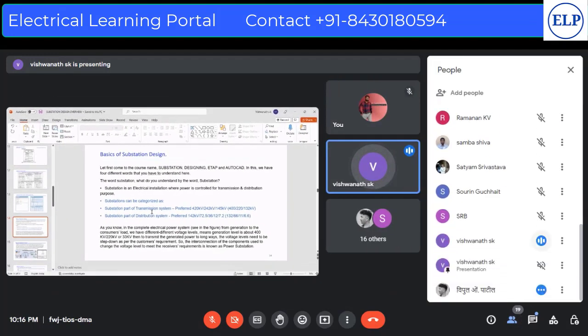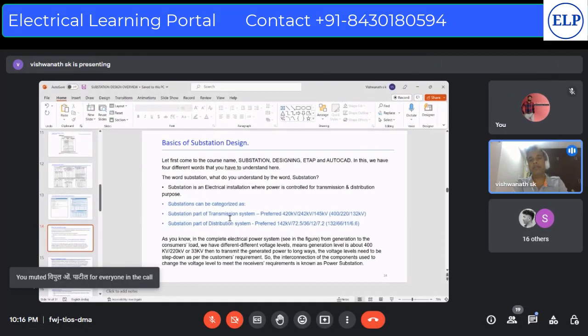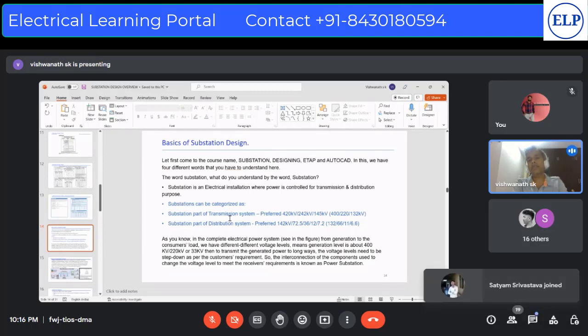For the substation at the distribution end, once it comes to 132 kV, you should check what kind of voltage is coming to the plant. Then further, it should be distributed at 11 kV or 6.6 kV. Always your motors are either 11 kV or 6.6 kV motors. Sometimes people also take a transformer of 33/0.415 kV or 11/0.45 kV. So the distribution voltage and converting it down to 11 or 6.6 kV is very, very important in terms of distribution.